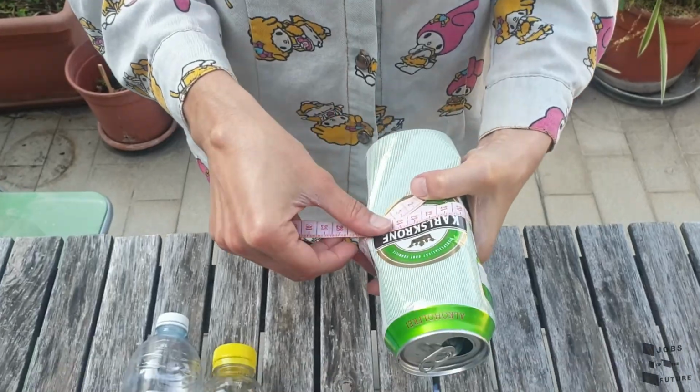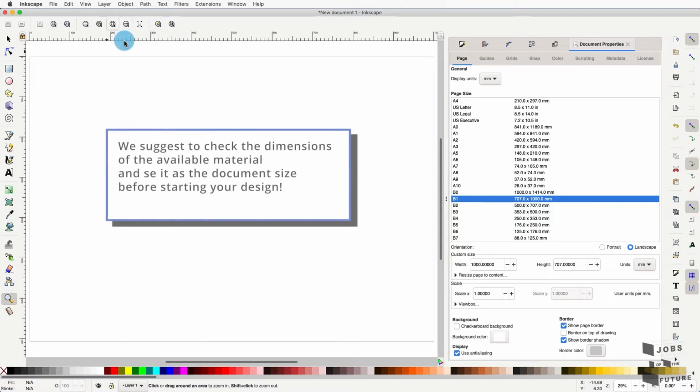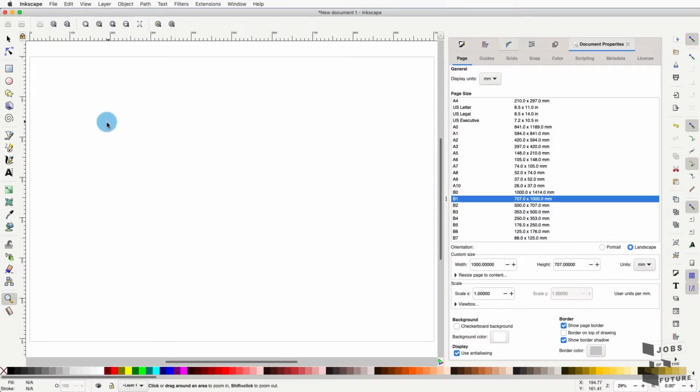And I measured that 7 centimeters diameter should be enough for every bottle to enter, because aluminium cans are standard size, but plastic bottles sometimes have some difference in shape, in contour, and so 7 centimeters should work fine. So I can start to design the circle, the inner circle where the cans and the bottles should be